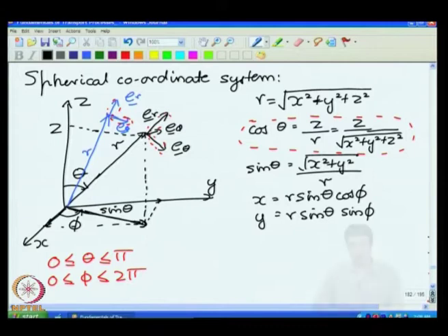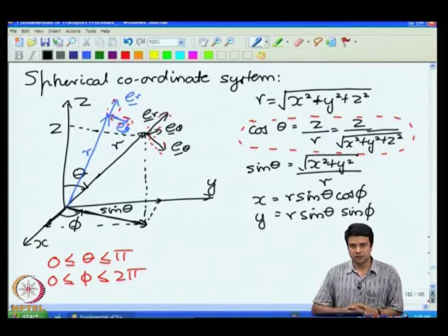However, if we could write down equations that are general for the particular coordinate system that we are considering, then it is now necessary only to straight away use those equations and write down boundary conditions and go about solving them. And that was the basic strategy that we were following for transport problems. We had identified 3 different types of coordinate systems: the Cartesian coordinate system, the spherical, and the cylindrical coordinate systems. And we went about writing balance equations for each of these coordinate systems.